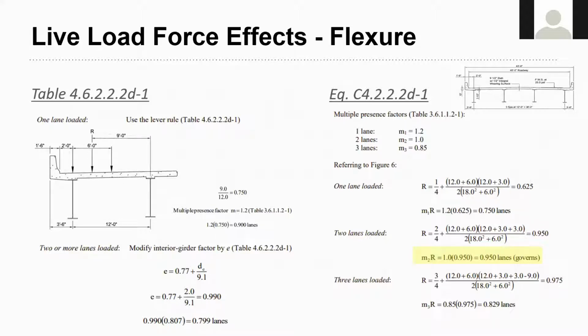I've read through the particular AASHTO section, the exact row, and the commentary for that special analysis. I took a look at the NHI course manual that was referenced, and also the Steel Bridge Design Handbook, which is also referenced. I can feel confident in developing the live load distribution factors for the exterior beams, in this case for 1 lane loaded using the lever rule, and 2 or more lanes loaded.